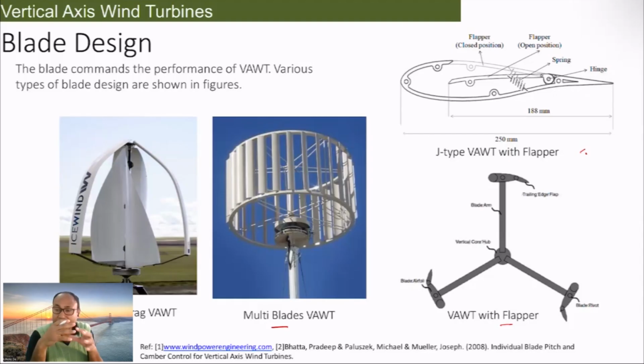You could have different kinds of blade designs, completely curved, twisted, helical, and different shapes, and different mechanical mechanisms to control the pitch. To be specific, it is an easily controllable system, because the size is way smaller than the horizontal axis wind turbine.